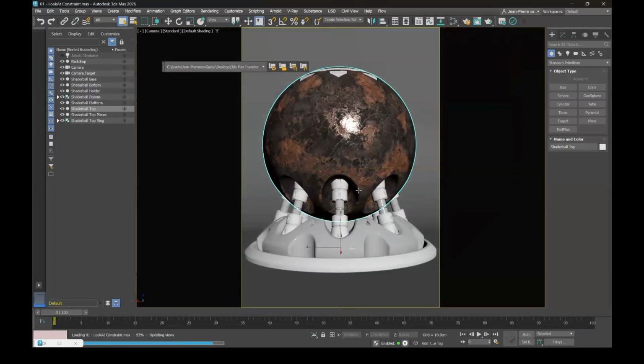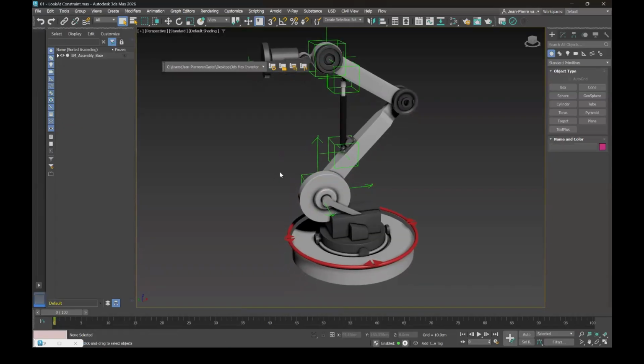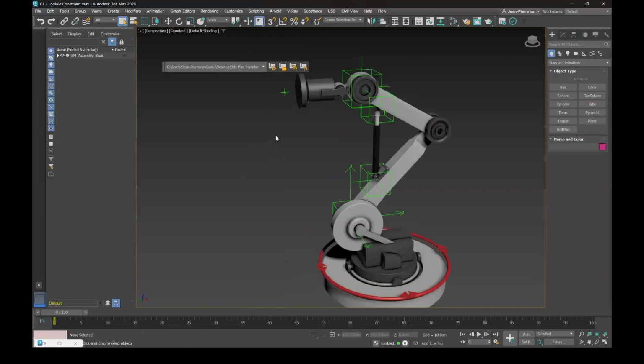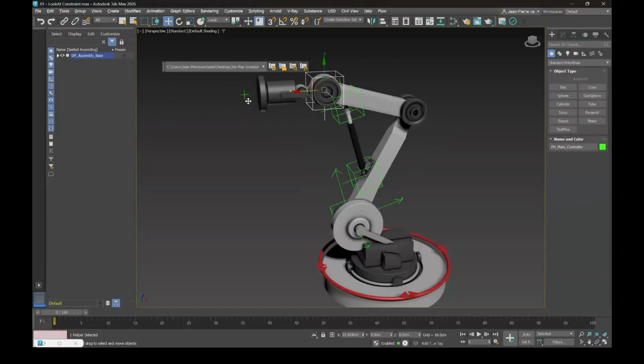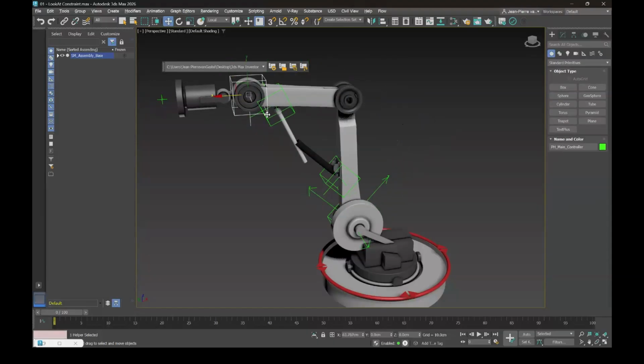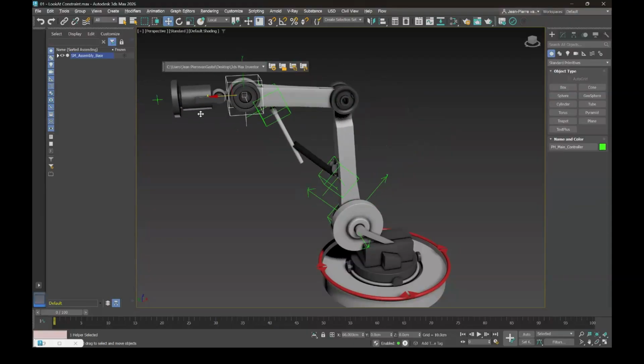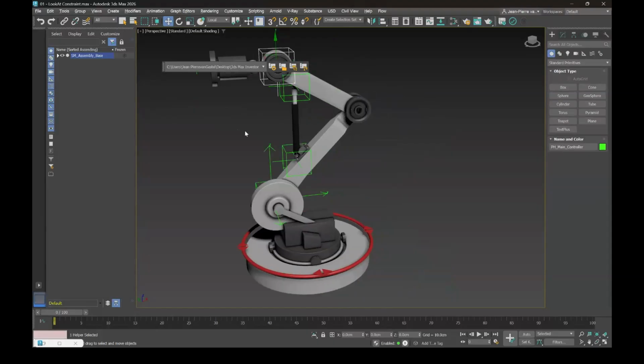Look at constraint. Imagine I have this set up. In this particular example, I repositioned the pivot point, which is based on the fixed constraint in Inventor. If I start moving this green box, which is a dummy object, just like helpers, the mechanism reacts, although the piston itself breaks. So I need to set up the piston connection. By the way, this movement is done by bones, so we have a bone system. Do we have time for that?